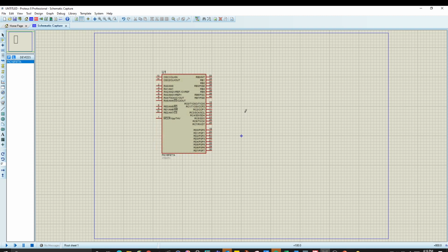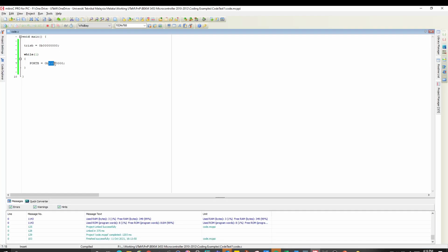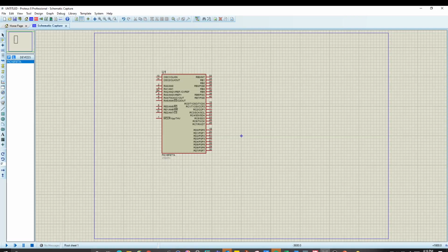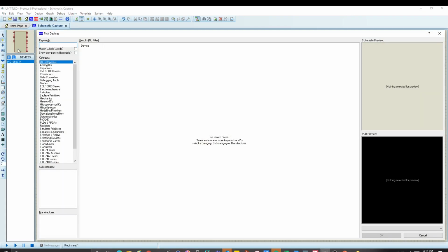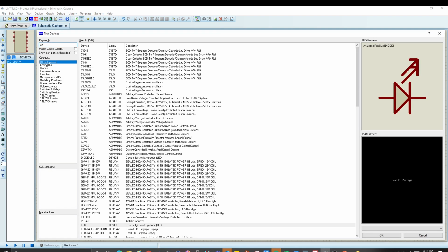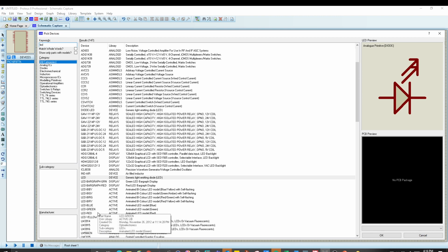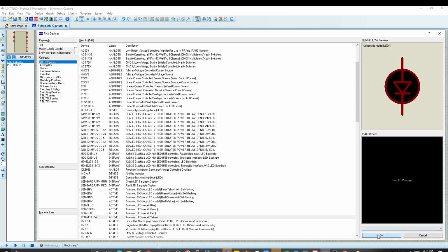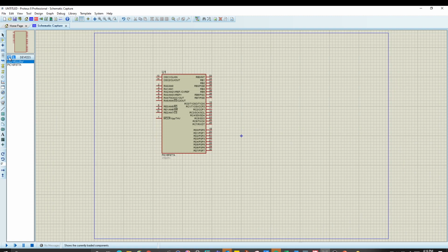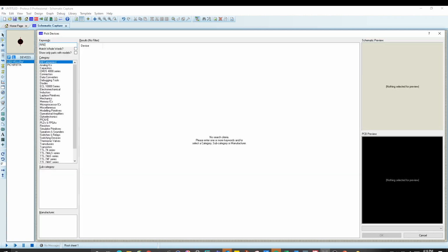So right now, you're going to just try to turn on the LED by having the command just now, by giving 5 volt here and 0 volt over there. Let's try to run another one. Take out the LEDs here. Do we have any LED here? Yes, this is the one. LED, just pick LED yellow. It's much easier for me to look at. Then you have the resistor.